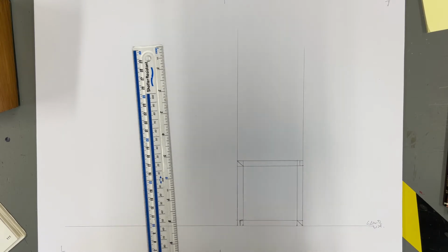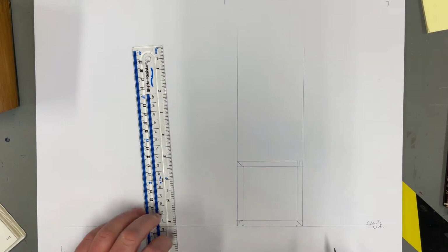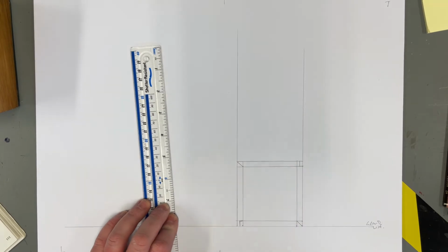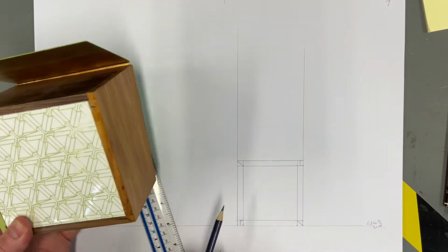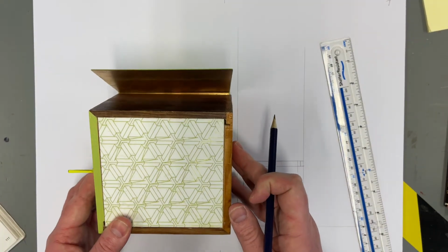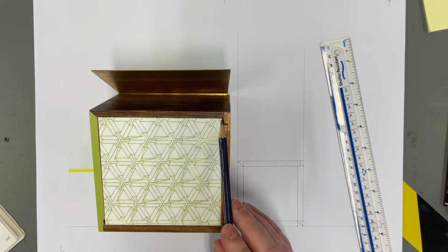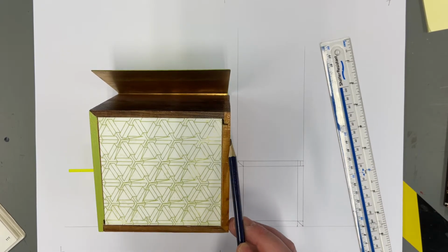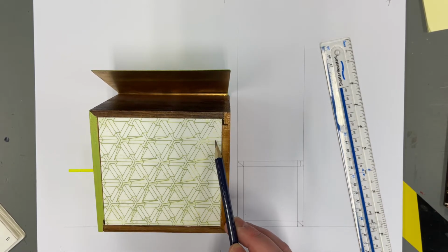Okay. Right, now that we've got that, we should also be showing where the plastic would go. Now, if we bring the product back on screen, you can see that the plastic actually fits into the wood. This wood is 12 millimeters thick, so it goes to about that size there. There's a little rebate joint in there that allows the plastic to slot in and connect to it.